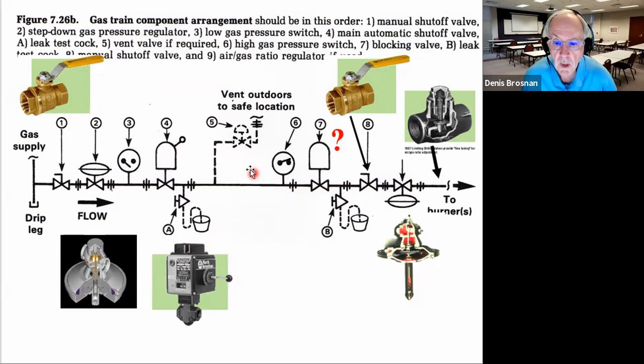So going forward, basically the main components are a ball valve to isolate the burner groups, a ratio regulator, and a gas trim valve. In the literature, North American calls this a V-port valve because of the shape of the little valve stem.